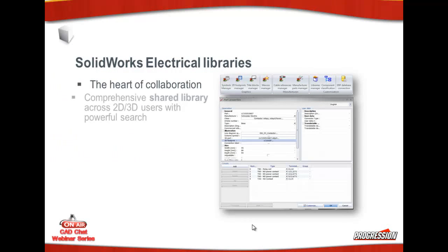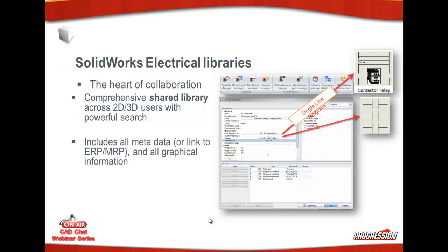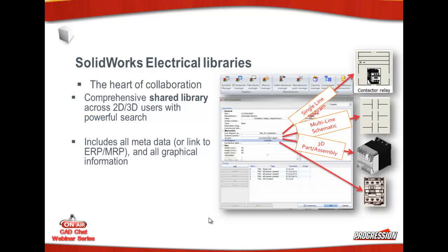Again, SOLIDWORKS Electrical is built on a SQL database. So the database contains all the intelligence. Each project you create is going to be a table in the database that keeps track of all the components that are needed for the wire links and all that information. It is in a shared environment, so the 2D side of things, the schematics, symbols are built in the database. Then you can link different tables in the database, so you can link a symbol to a SOLIDWORKS model, for example, and also to a manufactured component. So everything is then tied together.